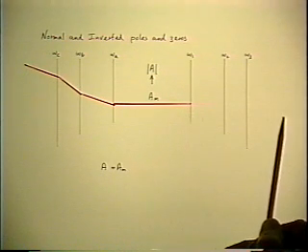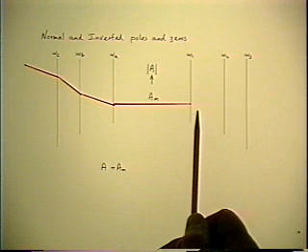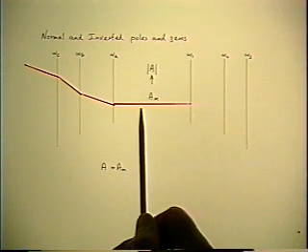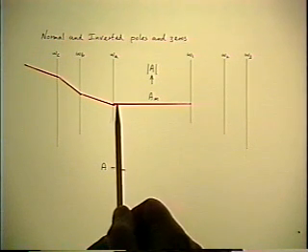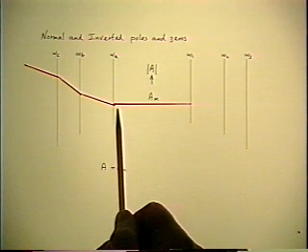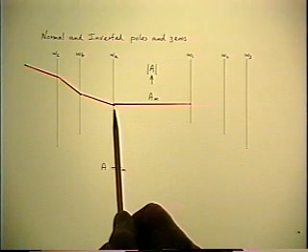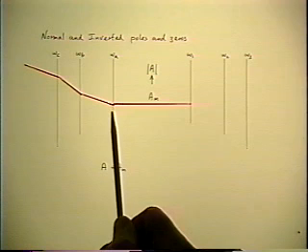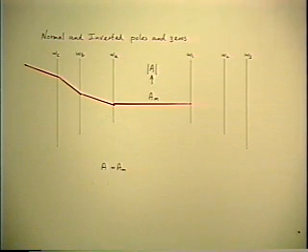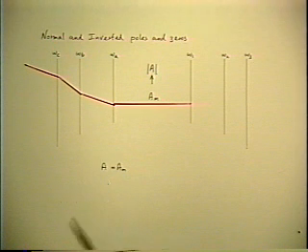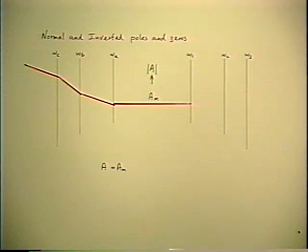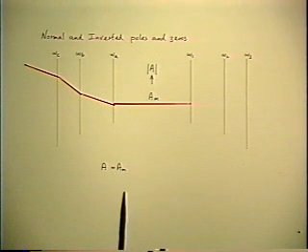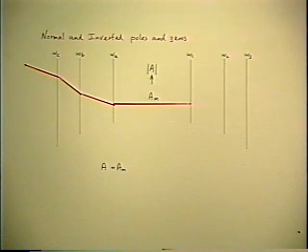And you look up in frequency and see if there's any corners, and there aren't in this case. So you look down in frequency, and the first thing you encounter is a concave upwards corner. And the only two questions you have to ask yourself are, does it bend up or does it bend down? And are you going up or down in frequency? And you answer those two questions, and it tells you what factor to write in each case.